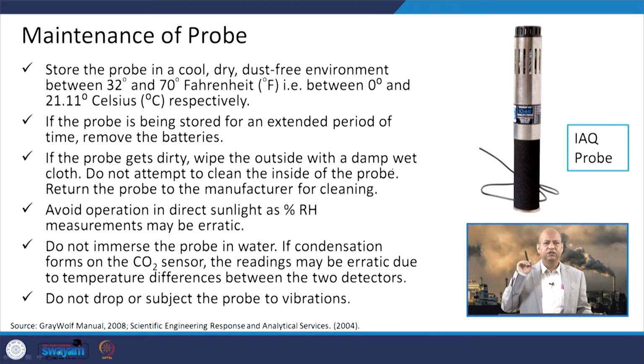So, better give it to the manufacturer or their agents, they can clean it properly following the proper protocol and they can give it back to you. Otherwise, just clean from outside using a damp wet cloth. Also, we need to avoid operating this sensor in direct sunlight, because otherwise it will influence the relative humidity reading.